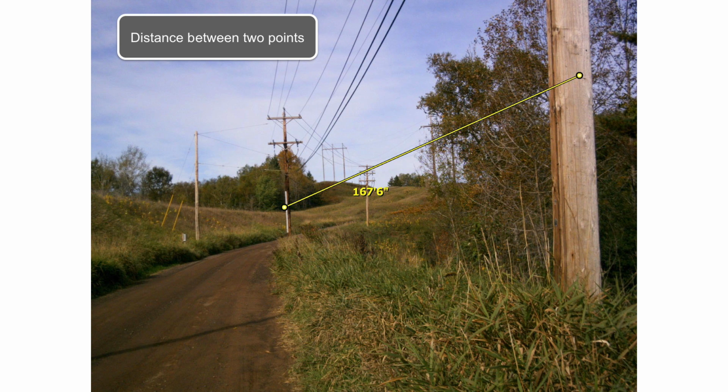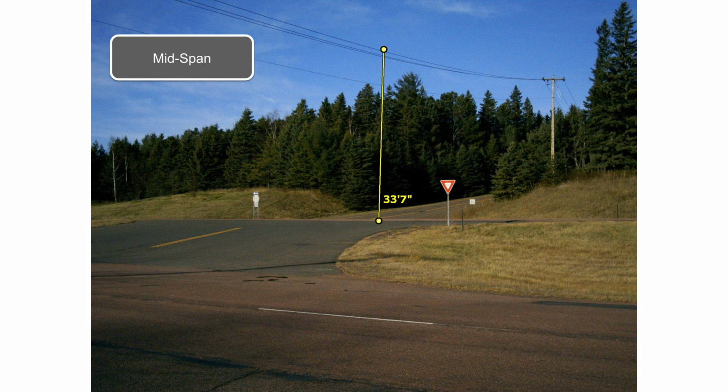This is a span between two poles. While we're capturing this data, we're able also to capture various pieces of information like azimuths to calculate angles for service links and angles coming off of poles, which our customers find important. Midspan, from the safety of the road, the person's able to shoot the wire, calculate the perpendicular distance without having to necessarily stop traffic or be actually in the road.